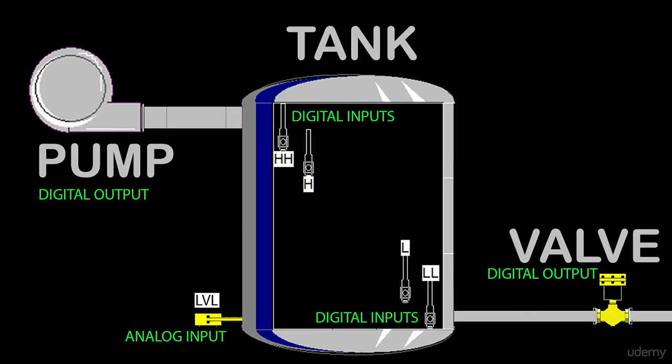In case you don't remember the process control section of PLC 1, low and high are your normal process control set points. At any time, your level inside the tank should be as low or as high or somewhere in between, but it should never be below low and it should never really be above high either.